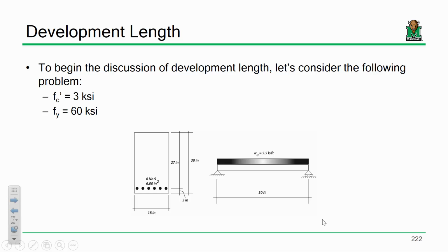And I have here the loads factored. We'll say it's like 5.5 kips per foot. So if we were in beam design mode and we were trying to design the size of the beam, or determine the amount of reinforcement, one of the first things we would do is compute Mu. If you have a simply supported beam and a uniformly distributed load, what's your Mu going to be? By now, that should be old hat. wL squared over 8, exactly.